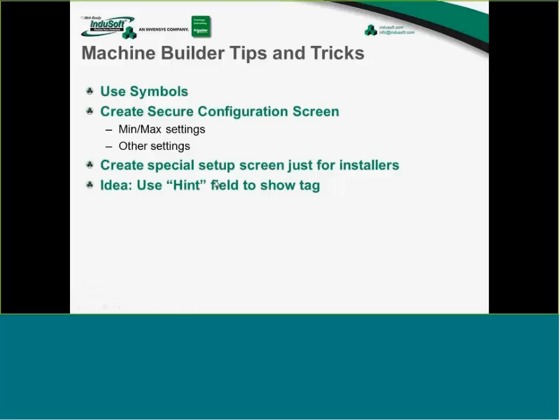So again, use symbols not only for the custom property aspect of the symbols, but just for a graphical, common look and feel. Another concept for machine builders that I always like to present is to create a secure configuration screen. Put some security on a configuration screen and allow yourself to put in there things like set points, or min and max settings.